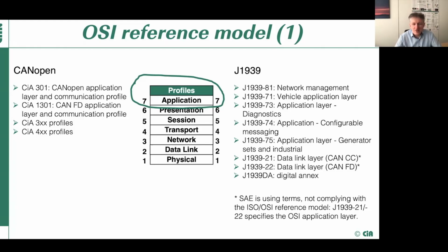Our members who designed CANopen devices and J1939 devices actually needed, for their J1939 truck-mounted and other vehicle-based systems, to have data from CANopen-based applications, which are already a part of the vehicle, and an opportunity to communicate into the J1939 network. So just look into the things CANopen and J1939 offer in the application.